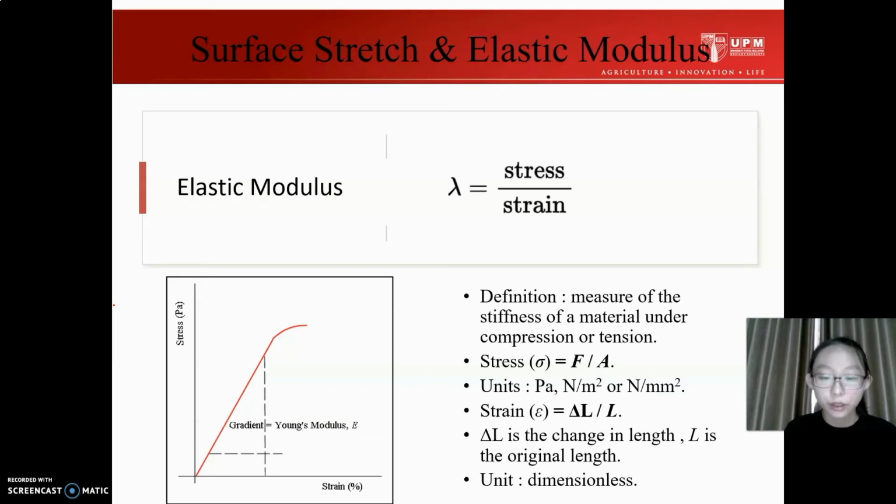After passing through the elastic region and through the yield point, the material enters a plastic region, where it exhibits permanent deformation even after the tensile stress is removed. So here is the elastic deformation. Here is the plastic deformation, and when it reaches here is the fracture point.